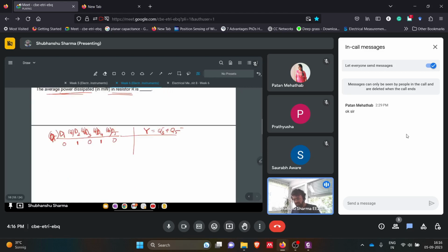So this is basically acting as a shift register. For the next step, the 0 will be here and everything will shift by 1 bit like this. For the next step, again this will be 1 here, this will be 0, 0, then 1, 1.